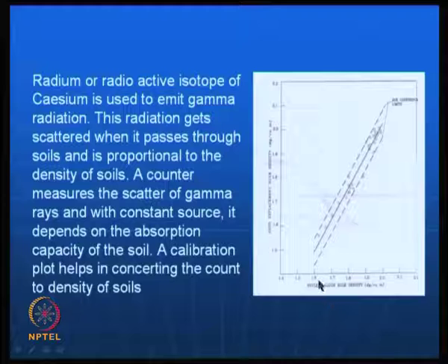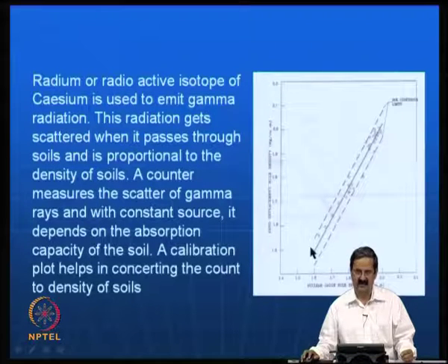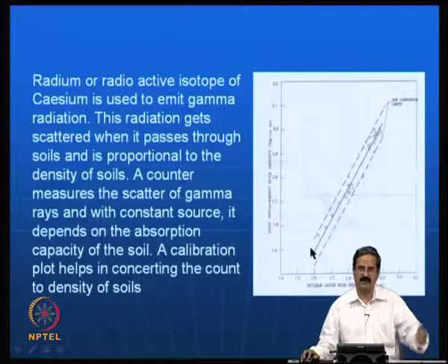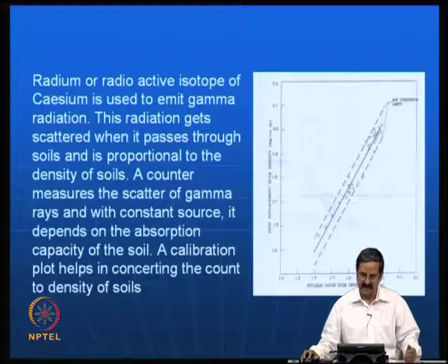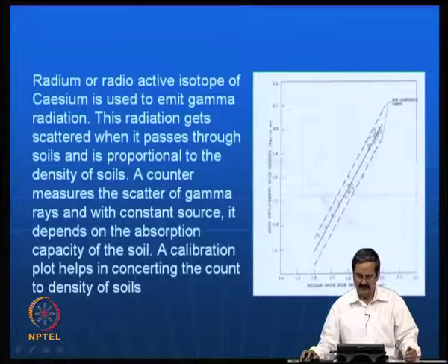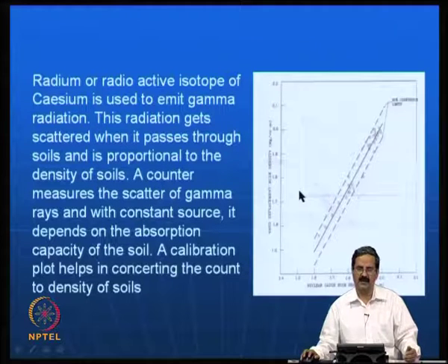One is using the nuclear method, the other is using the standard method. Once you do that and plot a relationship, these are all 95% confidence level lines on either side, and one can use that information very appropriately. Suppose the soil is of borrow pit material which has supplied a lot of quantities, then you develop this sort of method. The quality control is very easy.